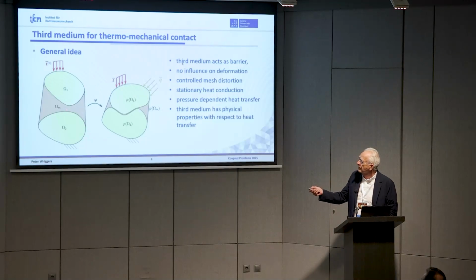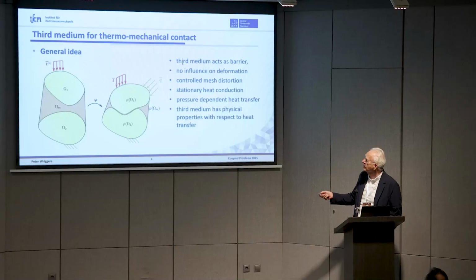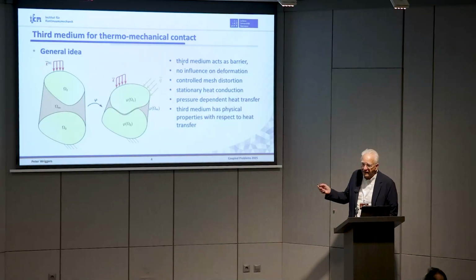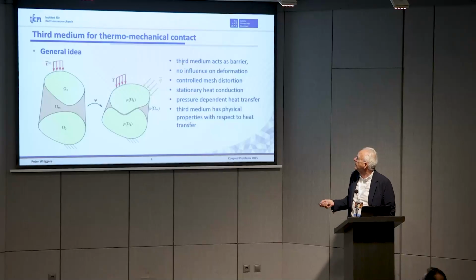The thing is, the third medium, of course, should not have any influence on the deformation once there is no contact. If it's not close to contact, otherwise you will see a deformation which is non-physical. So it should only act once you have contact. You have to control mesh deformation, because if you squeeze the stuff together like hell, the mesh does something weird eventually. We will see that.